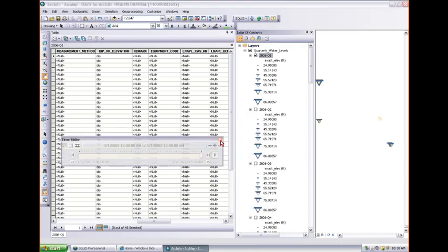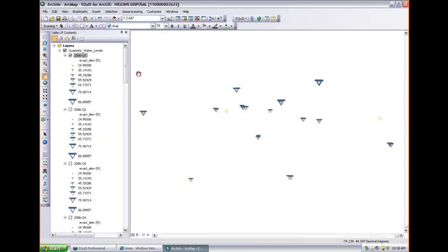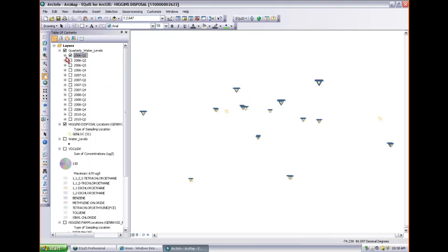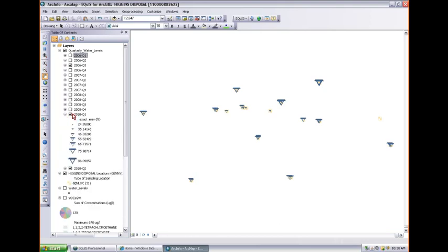If you wonder where's my layer, it's usually because you've got that time snapshot on. That's why I didn't see any layers. So all these points now, this is a group layer. Each sublayer is essentially a quarter, right? So you can create a map layout window for all your water levels. Basically, you've mapped all your water levels in one operation.